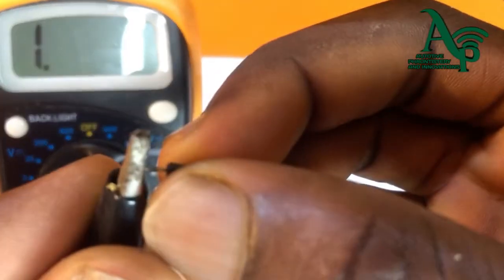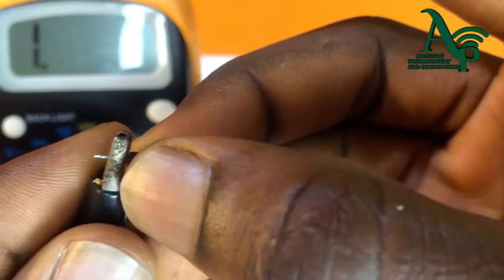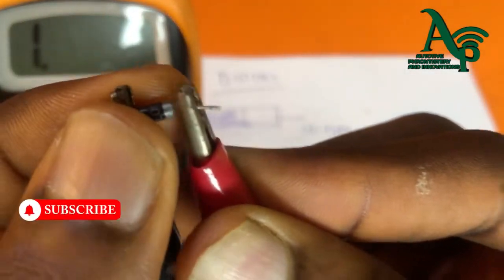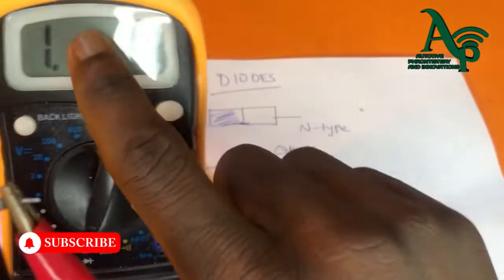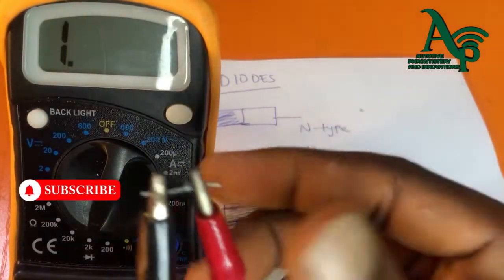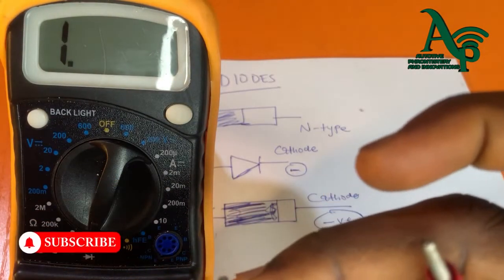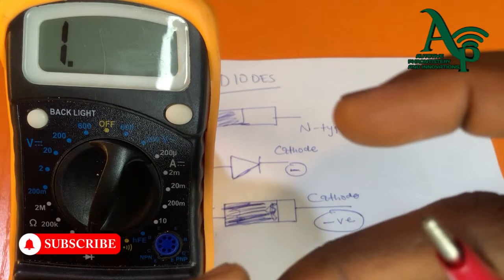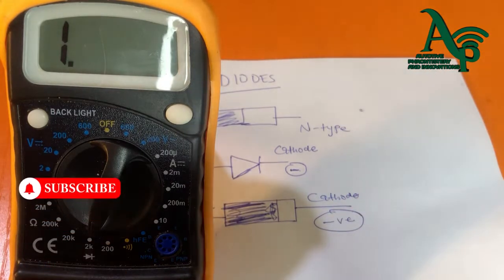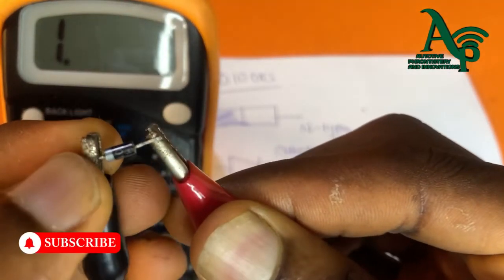If we reverse the polarity of the diode, or that is, we reverse the probes of the multimeter, we will not get any value on the screen of the multimeter, because the diode allows current to flow only in one direction. We only get a value on our multimeter when the positive terminal of the diode is connected to the positive probe of the multimeter, and the negative terminal of the diode is connected to the negative probe of the multimeter.